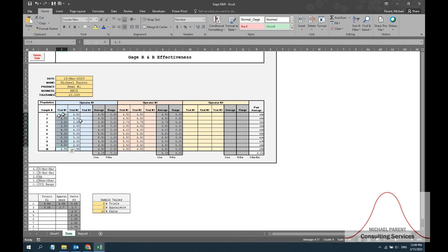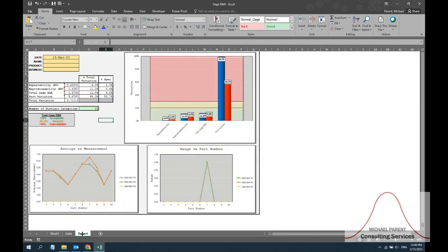So this is kind of the data portion of it. We collect the data, we run some trials, and then what we do is we create a gauge R&R report. And there's three facets in this that are really, really important. The first one is the average measurement, which really shows how much for each part everyone agreed. In this case, we see that on average, each of these parts varied between the parts, right? Part number 4 had less than, say, part number 7. Maybe it was weight. I'm not sure exactly what we were measuring in this widget.